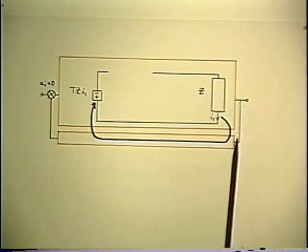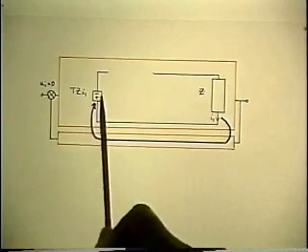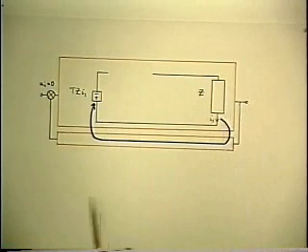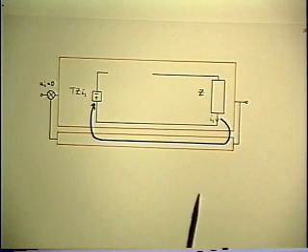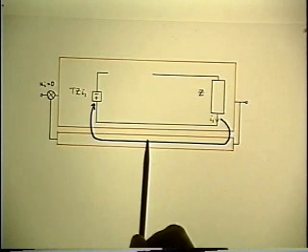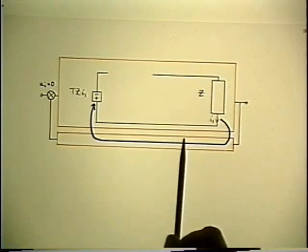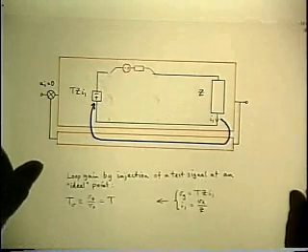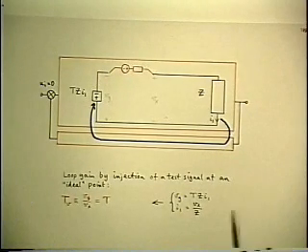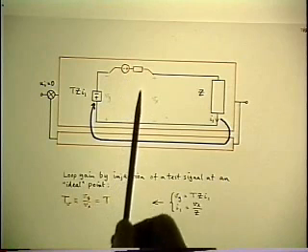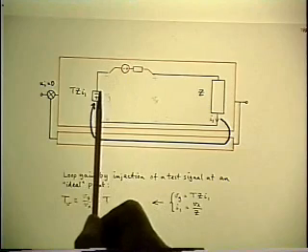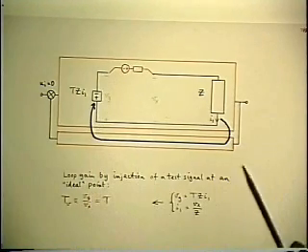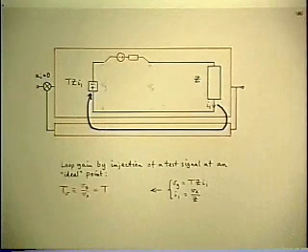All of the rest of the feedback loop we can bury inside this blue line again. We don't care about all the details of what goes on. But we do want to get into the problem where we start the right parameters that we want in the answer. So if we're going to do voltage injection at an ideal point, we've already shown this is equivalent to breaking the loop and applying the voltage at the same point. It's ideal still because we have a zero impedance out here. The first parameter to get into the answer is the loop gain, because that's the answer ultimately we're looking for.